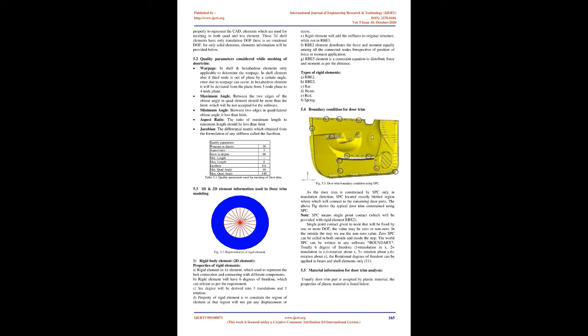He had studied the design and analysis methodology. The design adopts a plastic door module plate to replace the existing steel door module plate. These door modules were directly shipped to the OEMs, which saves assembly time and cost in mass manufacturing. The application of long fiber reinforced thermoplastic has improved structural and material properties over conventional materials like steel. The final design of the plastic door module is 33% lesser in weight with improved structure when compared to steel. The same can be adopted to replace semi-structural automotive parts currently made from steel.